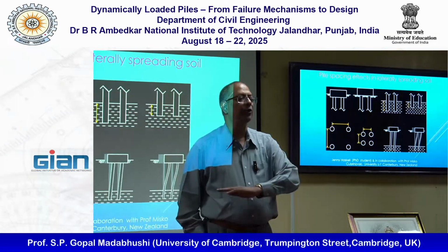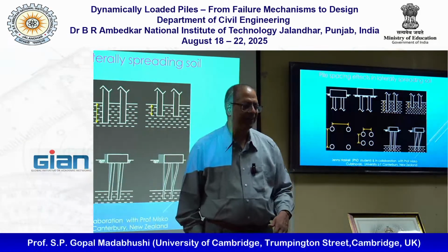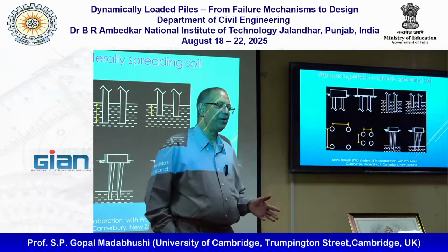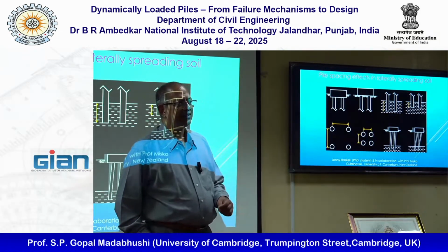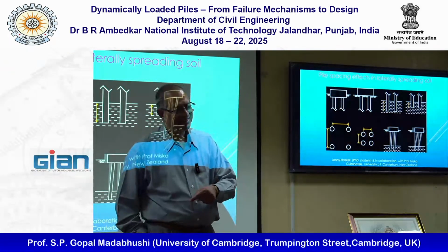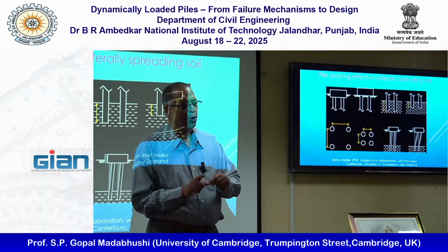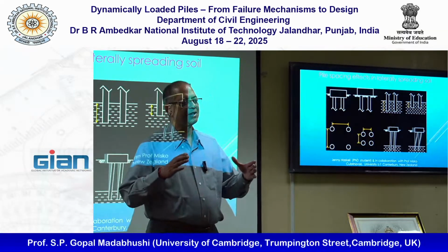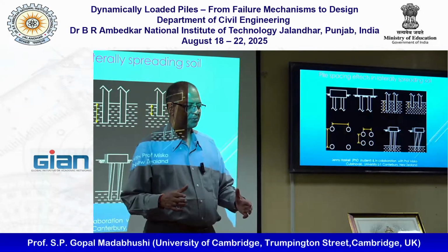Pile raft is, you got the raft covering the whole building area and you got piles. The big question there is the load, how much of the load is carried by the piles, and within that how much is end bearing, how much is shaft friction, and how much is carried by the raft.